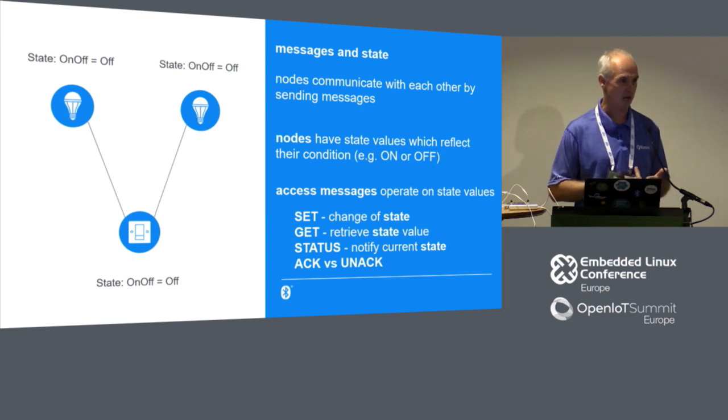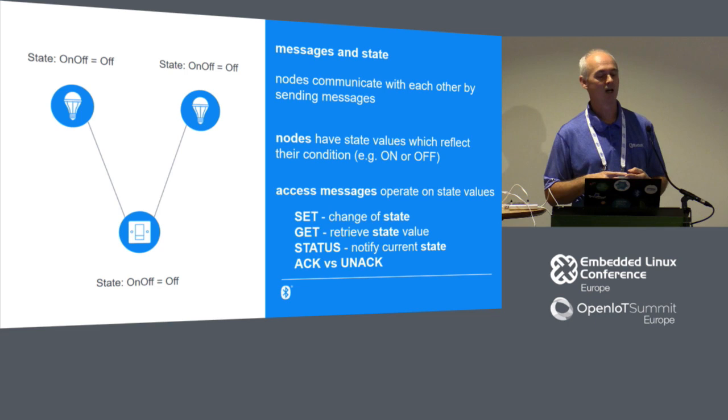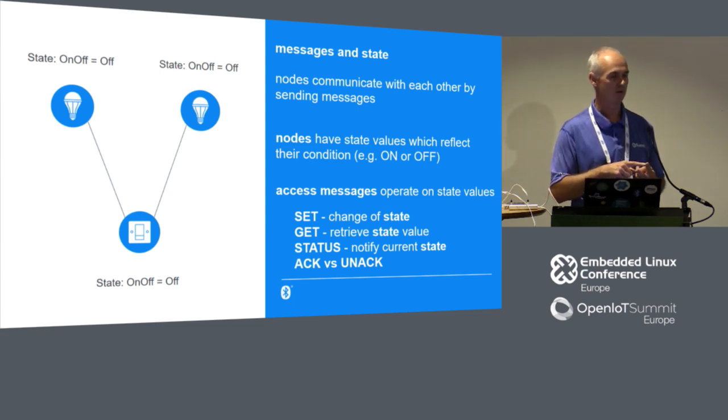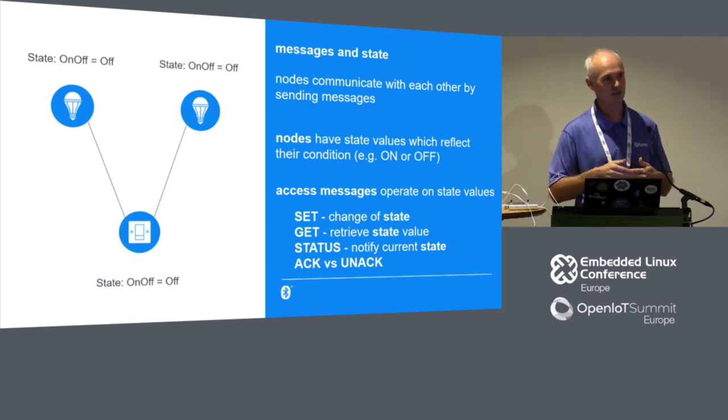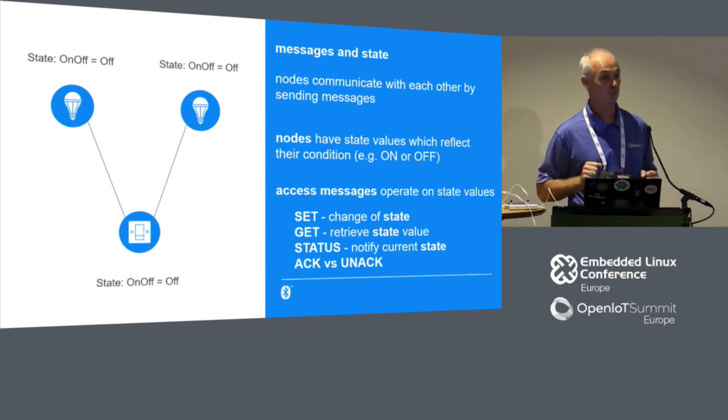And we played the probabilities game. So if there's a 0.05 probability of a packet collision, for example, just to make up some numbers to try and explain the argument here, then the probability that 2 packets transmitted in rapid succession will collide is 0.05 times 0.05, quite a small number. If I actually transmit 3 at 20 millisecond intervals, now we're into teeny tiny probabilities of collisions and therefore message failure. So we play the probabilities game with this repeated message injection, very fast, and that is one of the ways, that plus multipath, that you get really reliable performance.